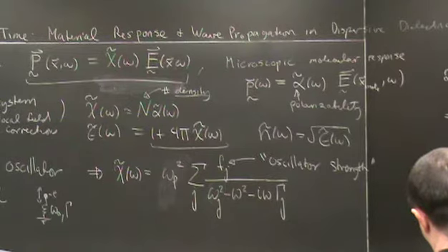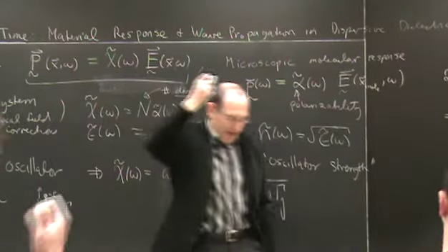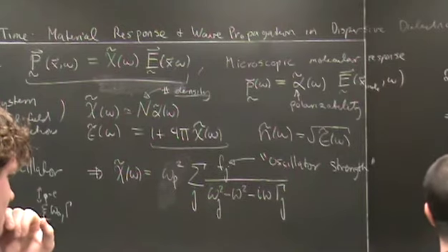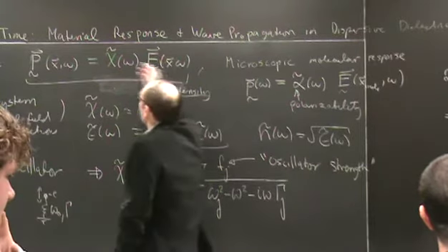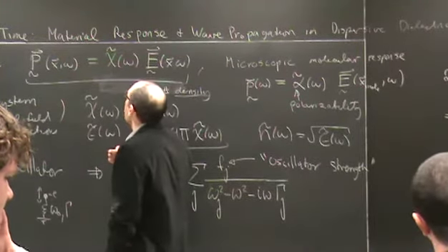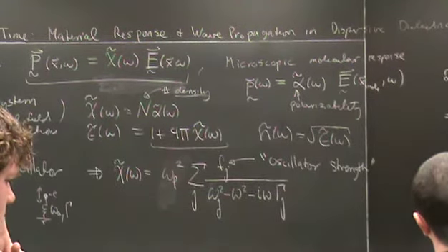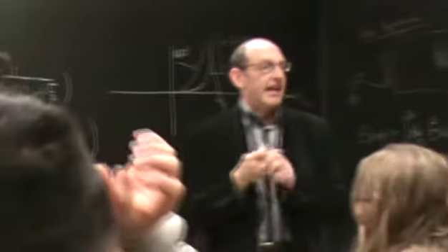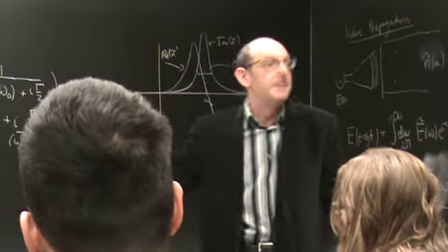Now again, the point here is that we're looking at the response at a particular frequency. So we should be thinking about this, as we will in a moment, as the response in the frequency domain. That is to say, we can think about this as the Fourier transform. They're one and the same thing. We study frequency, which doesn't exist, where we have an infinitely long wave train, because that is a basis for expansion of a physical signal.